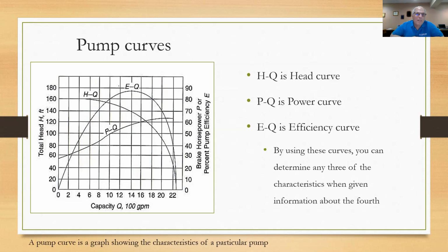You'd also find that if you continue to go down, you're going to hit the PQ line, the pump power line, and see the brake horsepower and all that. So you can just follow that curve at any efficiency and figure out where you're pumping and what your efficiencies are. So that's the power curve, the PQ line, all right?